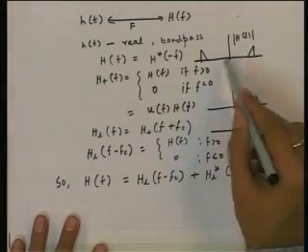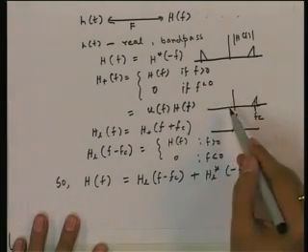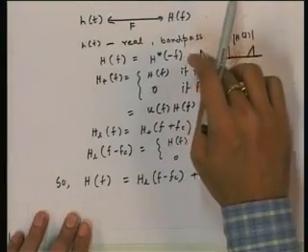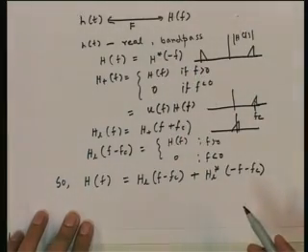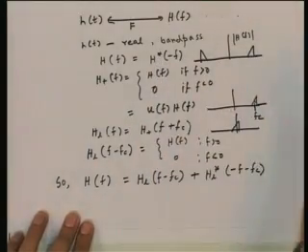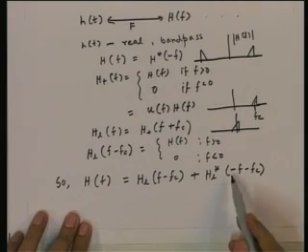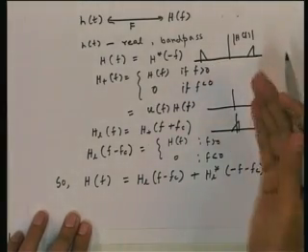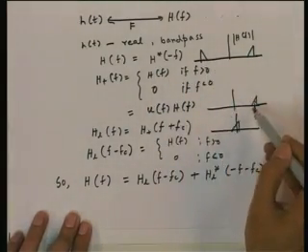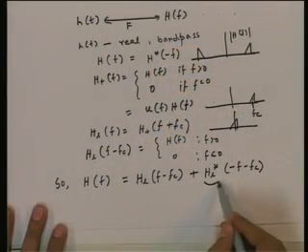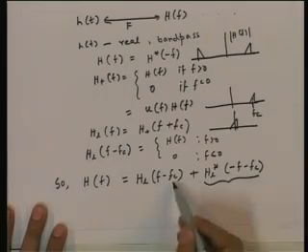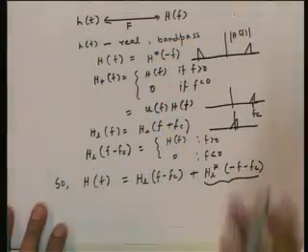So what did we have here? We want to get H(f) from this signal, H_L(f minus fc). How to get it? First keep this signal and then add this part. Now how do we get this part from this signal? First invert it: take the positive side into the negative side and the negative side into the positive side. We simply replace f by minus f, so that is H_L of minus f minus fc. But this is not really the negative flipped version of this signal. It has the phase negative of this, so you have to take the conjugate. The magnitude we want the same, but the phase we want negative. So we need H_L star of the flipped function. The flipped function is H_L of minus f minus fc, then we take the conjugate, so that is H_L star of minus f minus fc. Once we add these two, we get this function. This part is the positive part, and this part is the negative part. Okay.